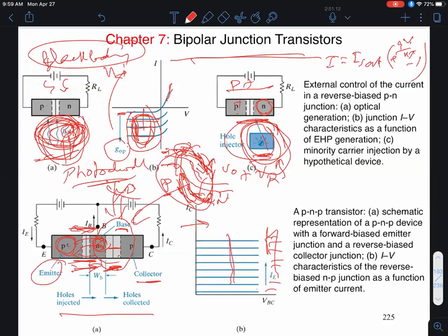Very good. Excellent. Okay. So if I want to double the hole current, a natural reaction would be I simply double the P plus doping. That would not do a thing at all, because remember, these currents are proportional to ni squared over Nd, say on the N side. Okay, that's my minority carrier hole current on the N side. So as you pointed out correctly, if I halve the N-type doping on the N side, that doubles pn, and therefore I get more hole current, right? On the other hand, if I doubled the P plus doping, that does nothing to the hole current, that will simply reduce the back injected electron current by a factor of 2.